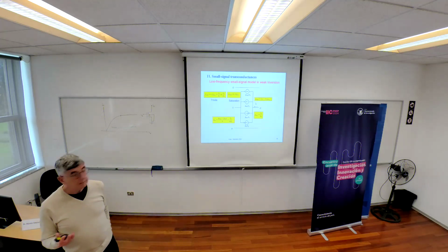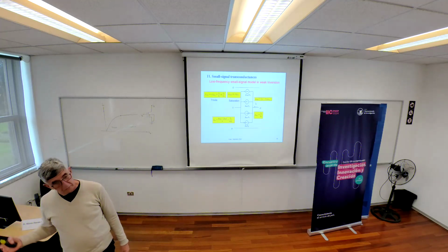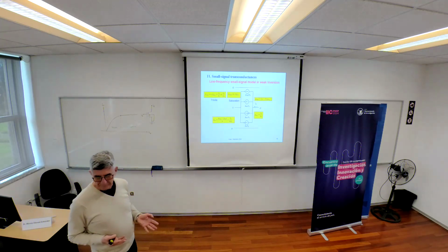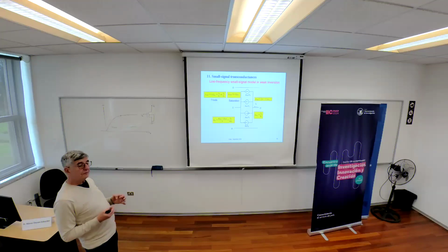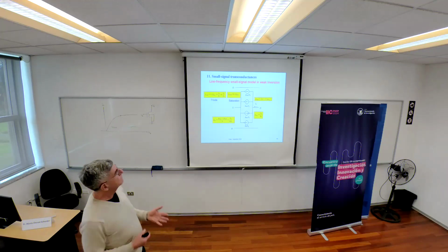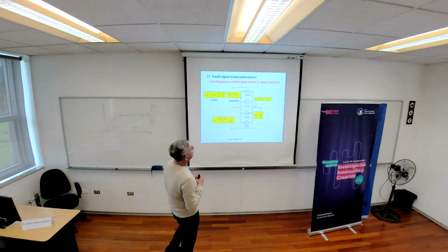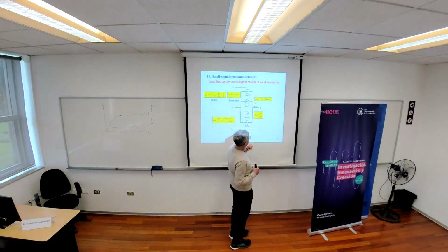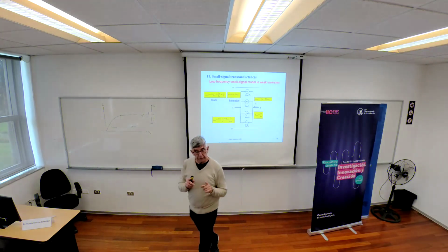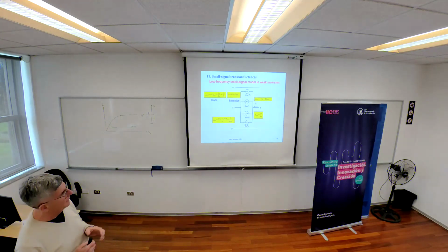What's weak inversion? The current is an exponential function of the voltage. So the derivatives are very simple. Okay? So you know that the derivative of an exponential is an exponential. Okay? So we have very simple expressions. Here, the first one, GMS. GMS is just IF over phi t. But what's IF? IF is not ID. It's a part of ID, okay?